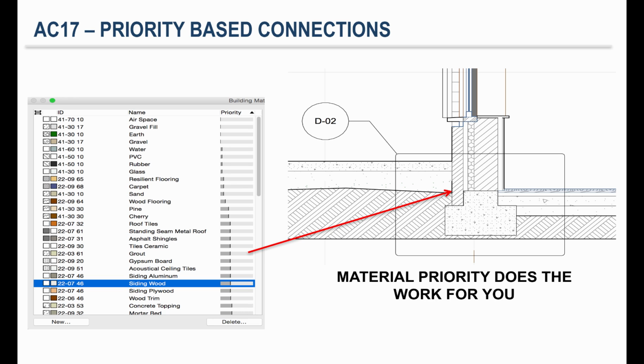The additional 2D drafting that's required at the detail level becomes annotations, dimensions, and maybe some small information that you wouldn't necessarily model into the project. In theory, we can model everything, but we also have to take into account schedules, time constraints, and fees.